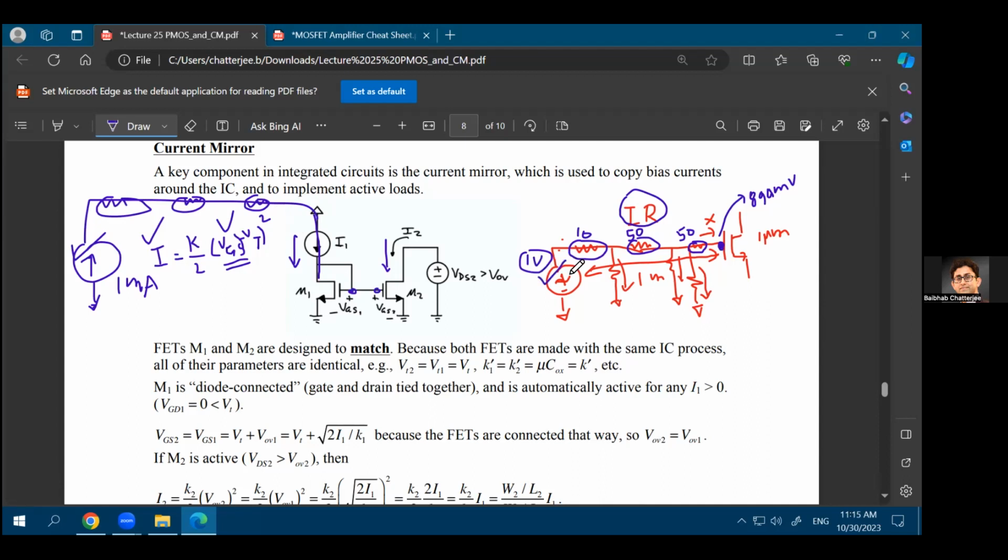So you're talking about the left hand side figure, right? So the leakage is not to ground, right? In this case, where are the paths where there could be leakage? From this point, there could be a leakage path to ground because these are physical devices, right? But from this point, there cannot be a leakage path to ground. Your wire does not leak to ground. The gate of the transistor can leak to ground, but not the wire.